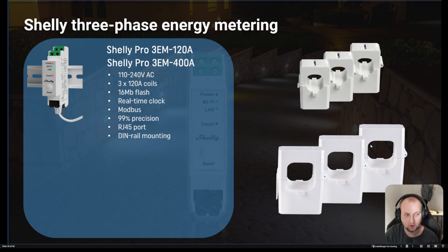on each current transformer. Again, very high precision, and the cool thing about these devices is that they cannot just monitor your consumption, but if you have solar panels or something like that, they can measure both ways. So it can actually measure what you are generating from your solar panels or windmills, and based on that, you can make some energy control inside your building.